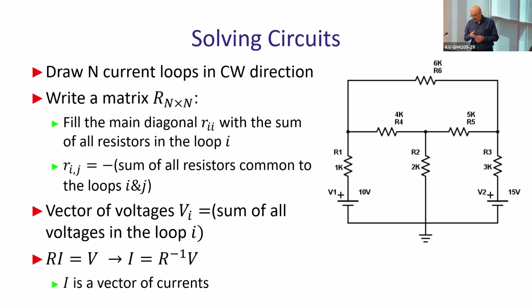More than that, you can expand the same idea to any capacitors, inductors, any elements which produce some sort of delays, okay? Store energy in a way, all right? So this works exactly the same way. You can think just about, instead of resistors, you will think about impedances. And you know that you can replace, for example, capacitor with 1 divided by SC, which is impedance.